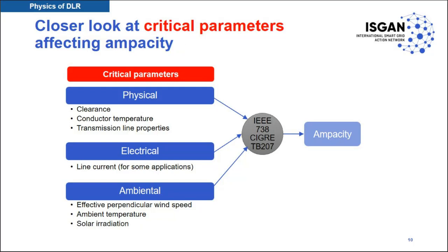You need your design properties to be able to know where your limits are, to make calculations on the available gains. You will need the line's load to compute the gains, and also for other applications like transient ratings.